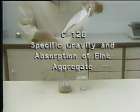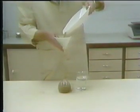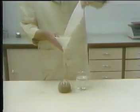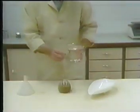Standard test method for specific gravity and absorption of fine aggregate. This method covers the determination of bulk and apparent specific gravity and absorption of fine aggregate. Bulk specific gravity and absorption are material characteristics commonly used to determine quantity and moisture content of fine aggregate in